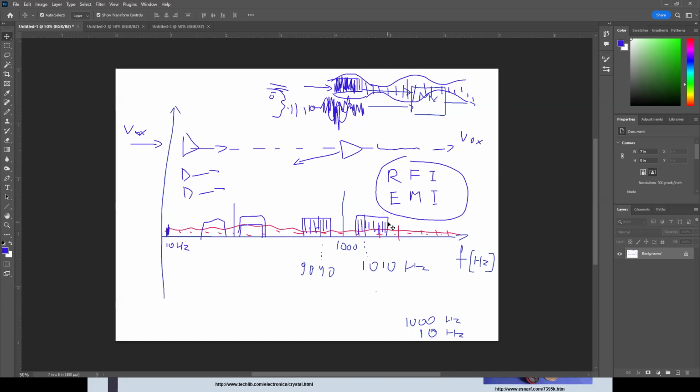But if you're transmitting only voice, then you can eliminate one of the sidebands. If you eliminate the lower sideband and you are transmitting only up, using filters, and you're only transmitting the upper sideband, and the upper sideband could have enough bandwidth to carry human voice, then you don't need that.